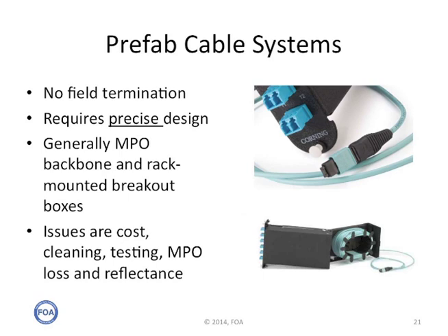If the system is prefab with LC modules, as shown here, testing is straightforward. But if you're installing parallel optics with MPO connectors, testing is more complicated. We're actually working on a page on our website and a video just on testing these parallel connections.